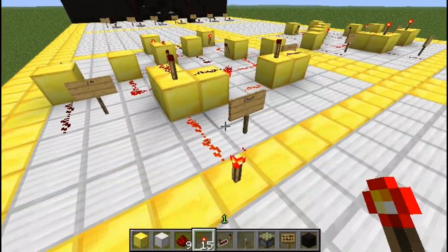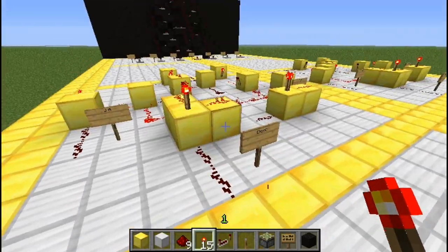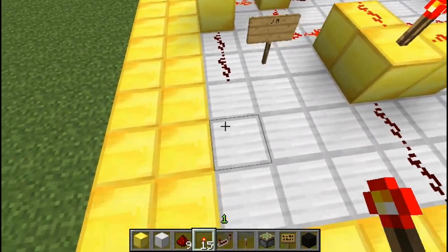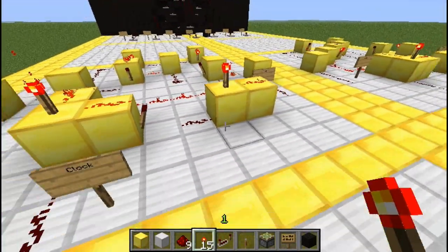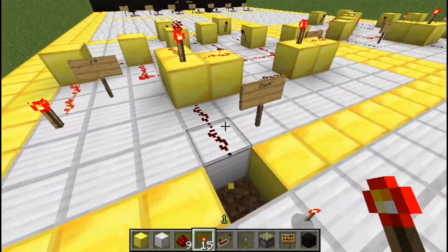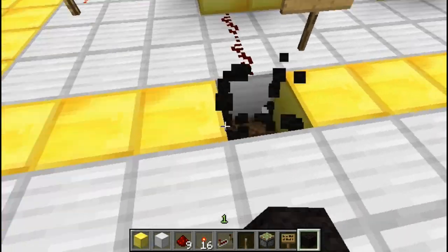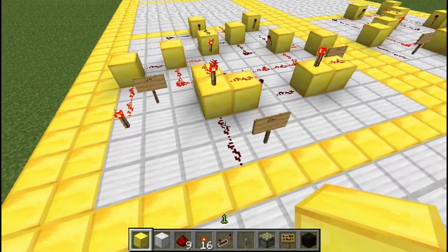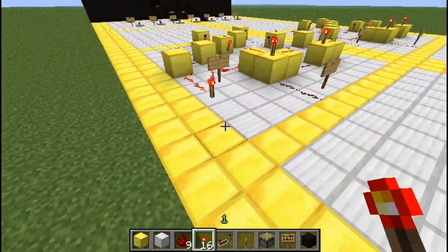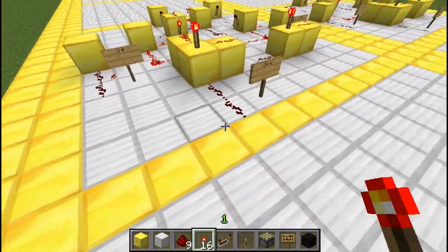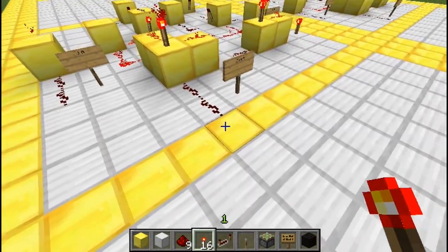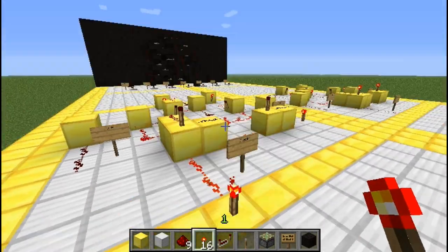You have a pulse coming, so there's a pulse, and it stayed the same. So then if the 2 inputs are different, and you input a pulse, the output takes the value of J. So just input a pulse, the output is 1. So J is 1. And set K to 1 and J to 0. Now I input a pulse, the output is 0.